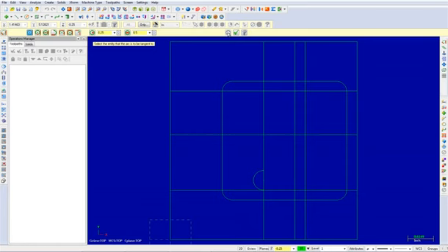Again, select the following horizontal line and then pick the intersection point. Pick the arc that you would like to keep. Select the following arc. Again, choose the Apply button to stay within the command. This time, choose the following horizontal line and then pick the intersection.